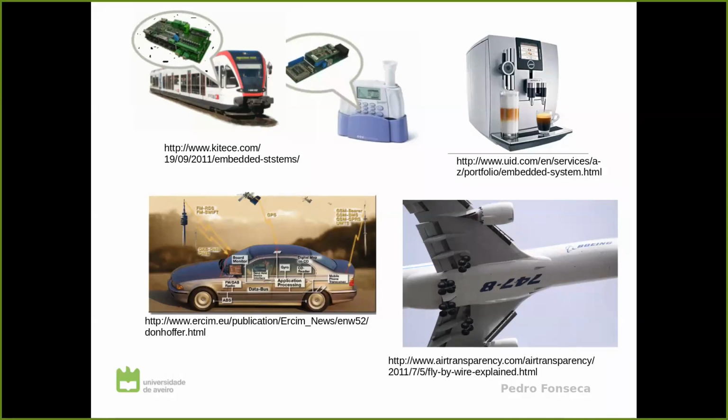And so the people from Boeing decided to introduce a system that would make some compensations on the settings that control the attitude of the airplane, in order to compensate for the tendency of the nose to go up, and it would force the nose to dive in order to improve the stability of the plane.